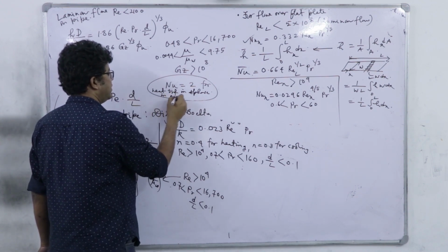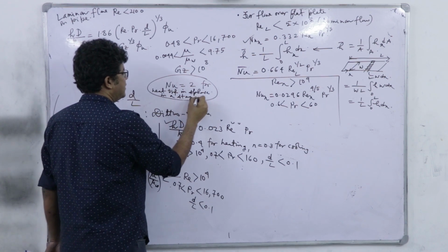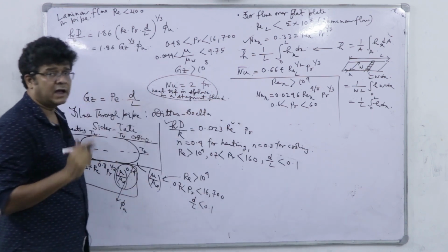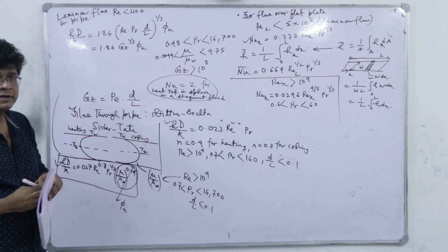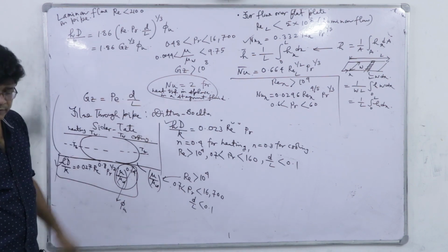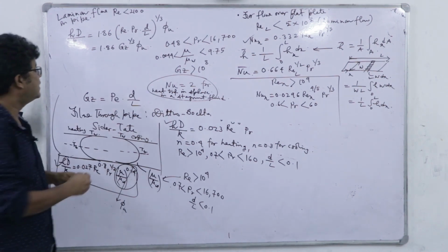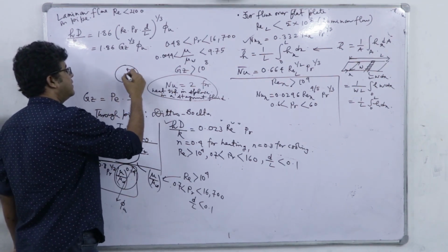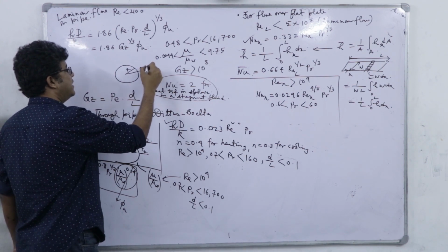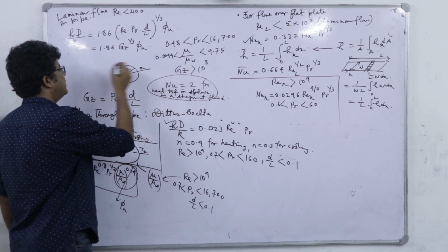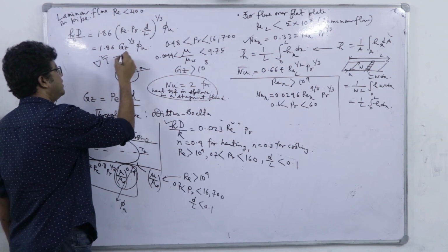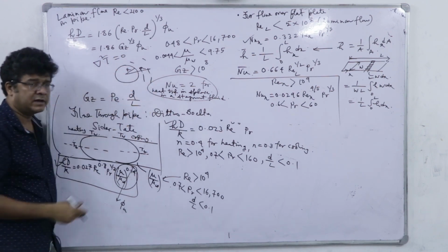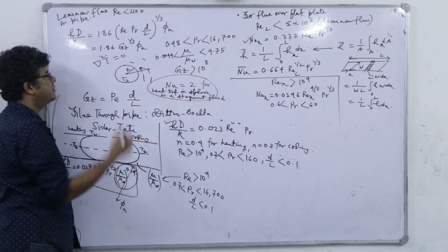in a stagnant fluid. So, this is simply conduction in spherical geometry, but we have to solve the temperature profile. How can we solve it? See, you take a sphere with radius R, and here we choose a radial coordinate. So, you solve this conduction equation in the fluid region, not within the solid. The sphere has a temperature Ts.